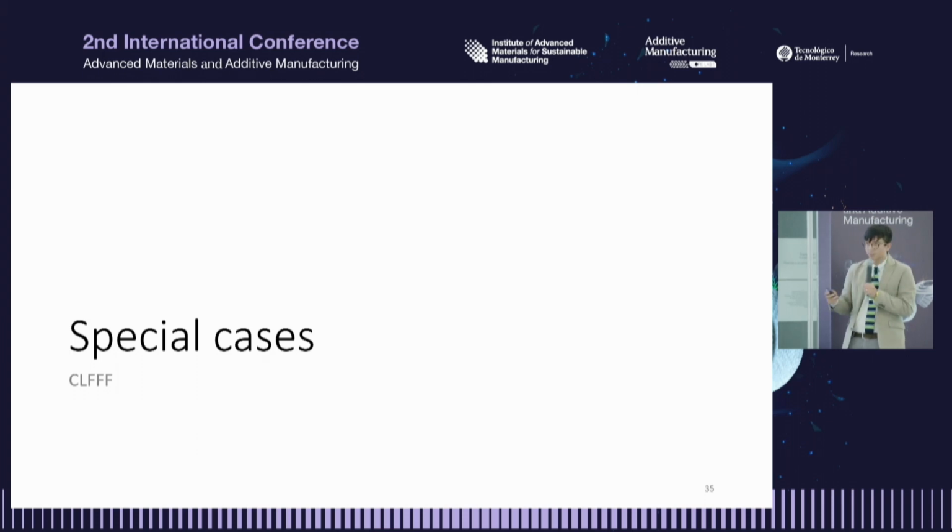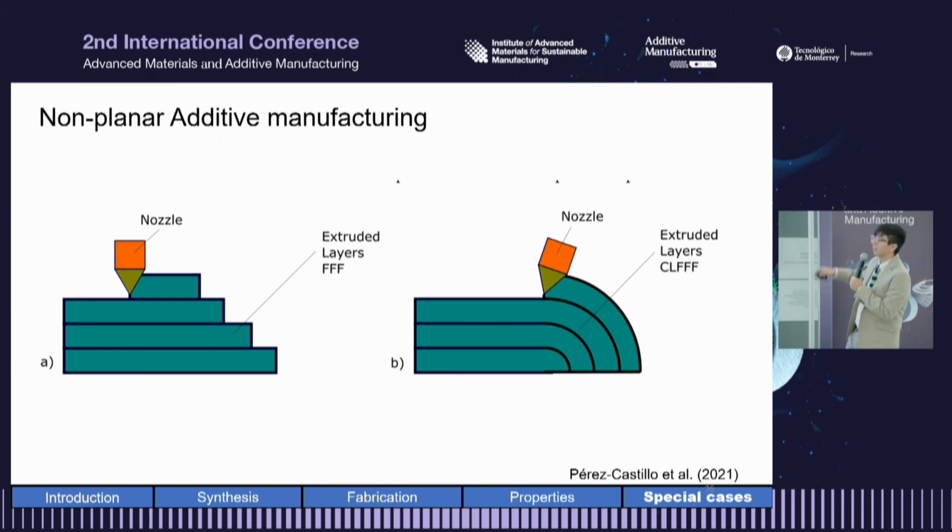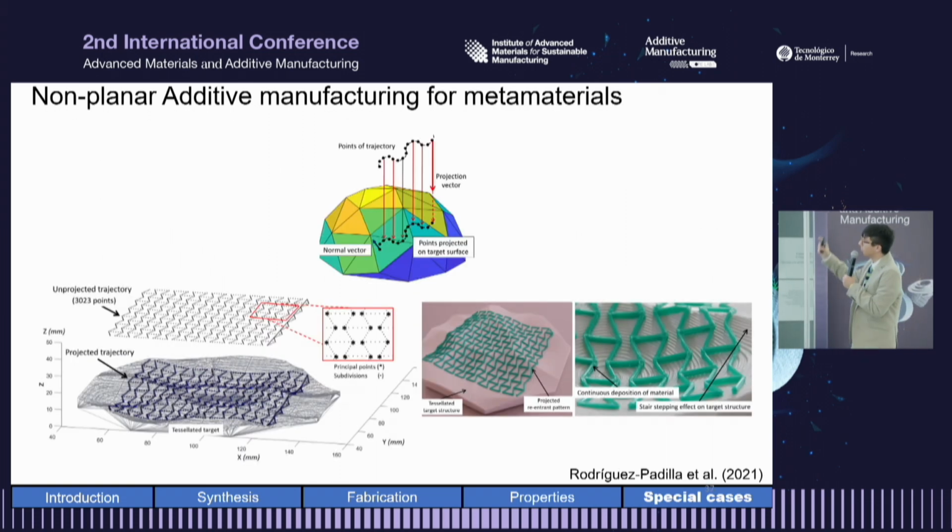And the first step to achieve that is being able to fabricate them using additive manufacturing that is not following the conventional flat layers stack, but to make parts with a stack of curved layers, like the one you see on the right. And for that, we propose an algorithm so that you take the 2D version of the cellular pattern, project that on the complex structure, and then with machines that have a higher degree of mobility or more degrees of freedom, you can actually print these things.